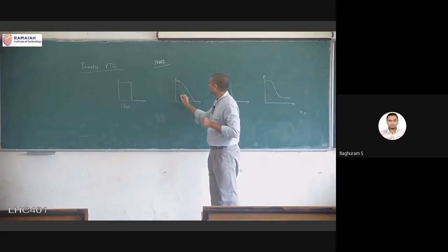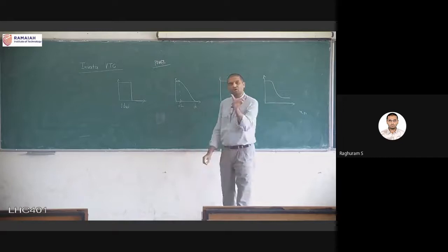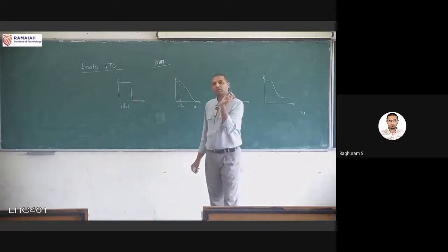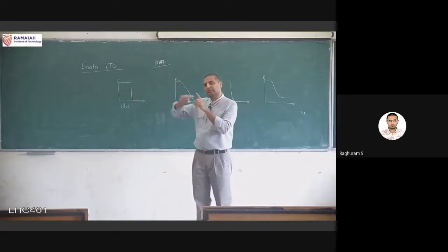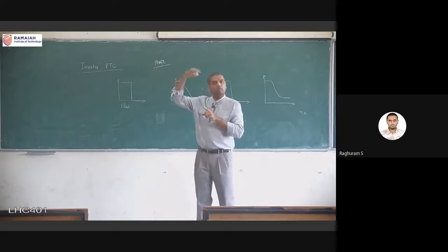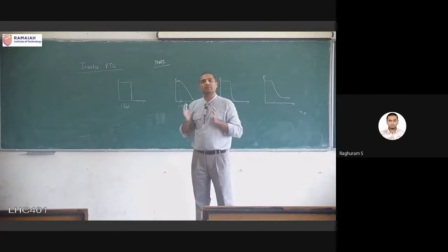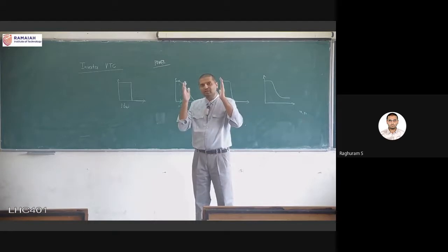This means that, say, this might be 0.2, this might be 1.8. So for this whole range of voltages from 0.2 to 1.8, that is when the input is changing from 0.2 to 1.8, or from 1.8 to 0.2 also, both ways, the power is going to be consumed, and that's very bad because this region from 0.2 to 1.8 is quite large.